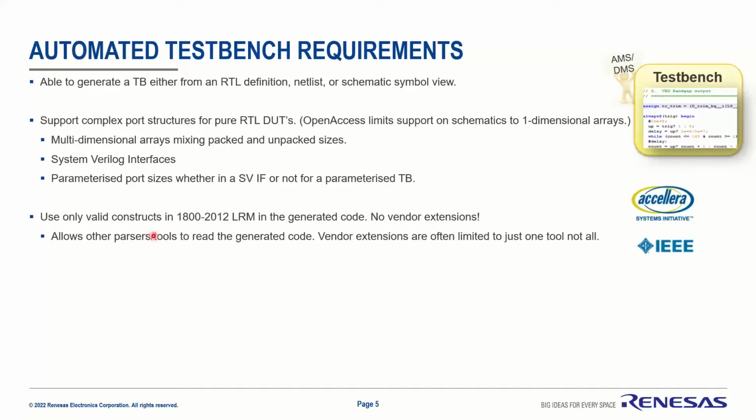The key thing is also to make sure that the constructs used are LRM compliant. Not only is this good practice, it means that you can use other tools to read the code, and vendor extensions normally are limited to just the simulator rather than the entire tool chain. So it's better to work within the LRM. If not, you get your LRM updated, rather than doing bespoke stuff.